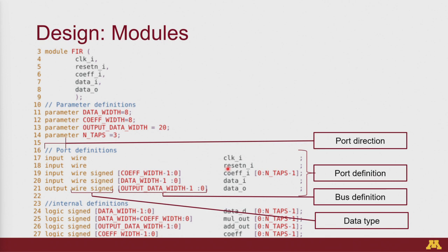Okay, so let's continue. Probably the last thing which I forgot to mention is that when you have multiple dimensions, like unpacked dimensions and packed dimensions, the order of it is a little weird. Normally we would think that it'll be left to right, but in reality the unpacked dimensions come first and then the packed dimensions. You can kind of understand why, right? The higher level dimension would be the number of wires, and then the lower level dimension would be the bits in the wires.